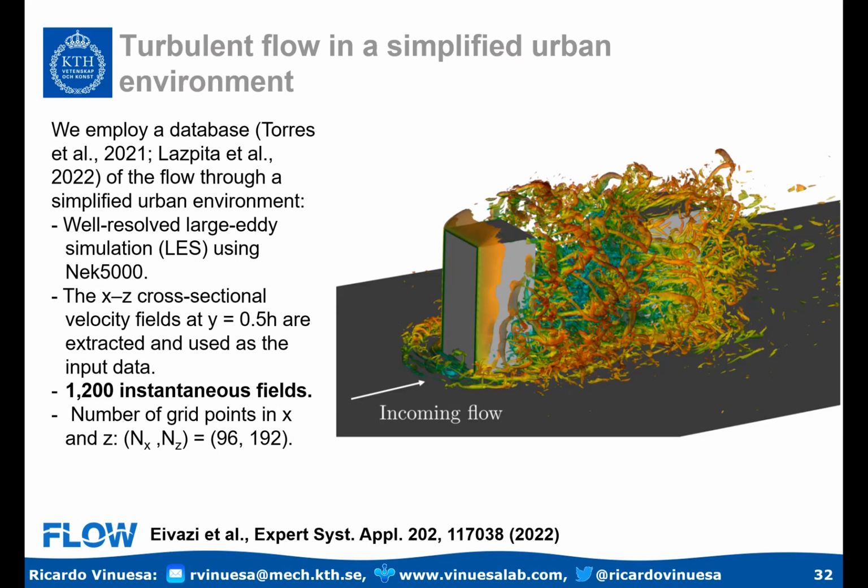The reason why I chose this flow case is that, on the one hand, you have wakes and shear layer separation, so POD should not be too bad because you have quite pronounced features. But at the same time, you have turbulence and quite some nonlinearity, which means that POD will not be perfect. You will need quite some POD modes. In fact, you need on the order of 400 or 500 POD modes in this case to reconstruct a good fraction of the energy. Of course, in an internal flow, it would be even worse. And we're going to see if we can do better with these autoencoders that I'm presenting today.